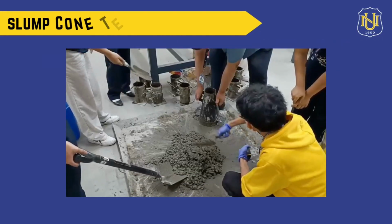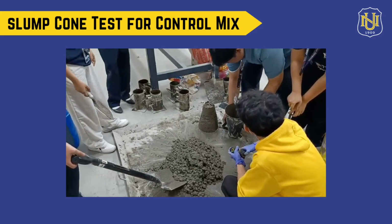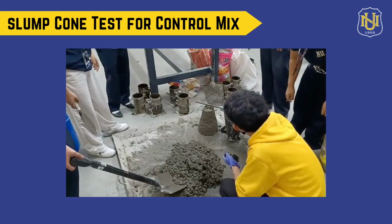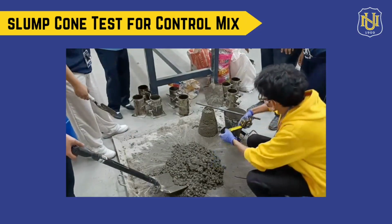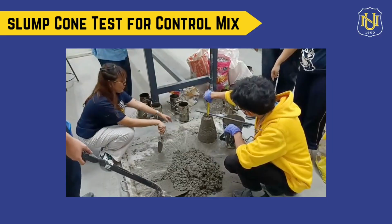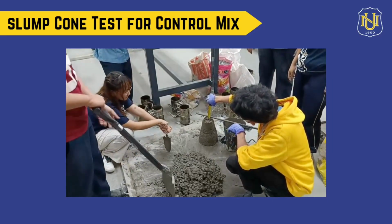A slump cone test was conducted to determine the workability of each concrete mixture. The concrete was placed inside the slump cone in layers and compacted using tamping rods. After lifting the cone vertically, the slump of the concrete was observed and measured.